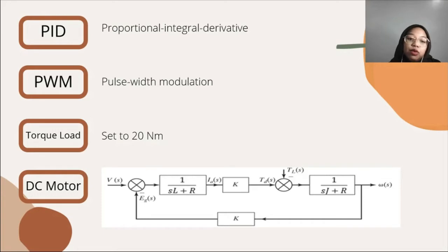The DC motor block uses manufacturer datasheet parameters, which specify the motor as delivering mechanical power at a no load speed of 195 radian per second when run from the 220 volt DC supply.